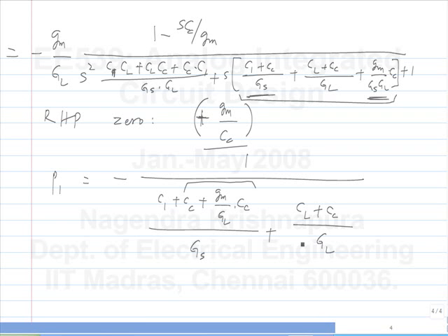But we have some extra term also. Why is it not exactly just this part? Why do we have the extra term? The problem is the regular Miller effect calculation assumes an amplifier with zero output resistance. If you have Cc, you will simply see Cc times 1 plus the gain, 1 minus the gain.